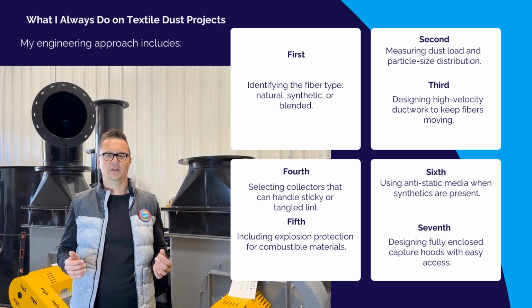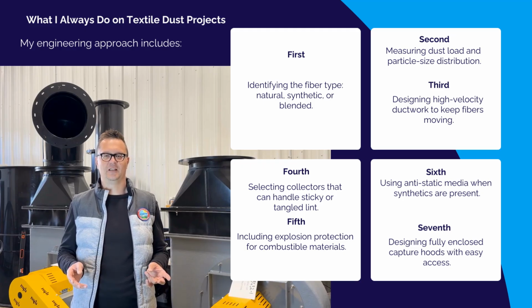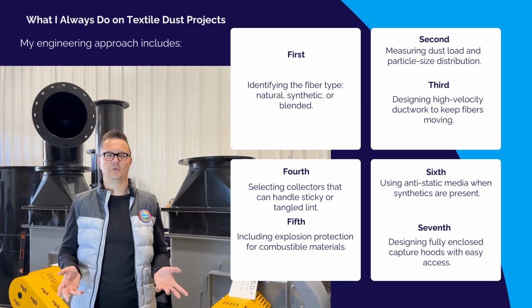Fifth, including explosion protection for combustible materials. Sixth, using anti-static media when synthetics are present. Seventh, designing fully enclosed capture hoods with easy access. This ensures safe, reliable, and compliant operation.